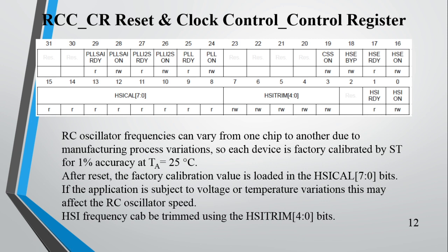That value will be loaded with the calibration value given by ST. And this calibration value loading to the HSI bits will be done automatically at the time of reset. We don't need to do anything.